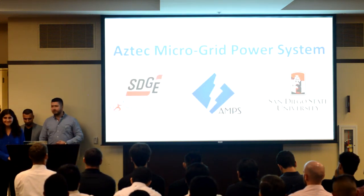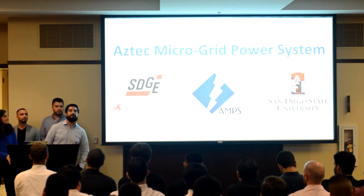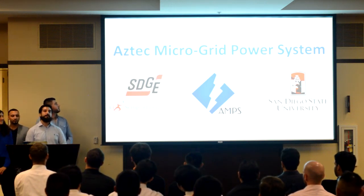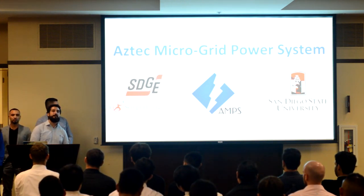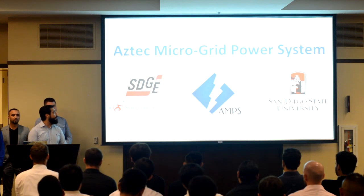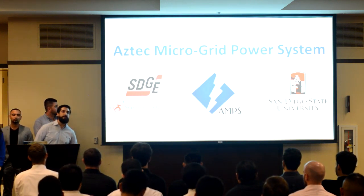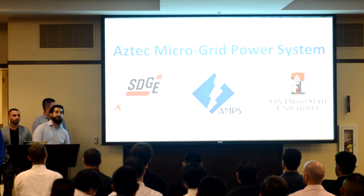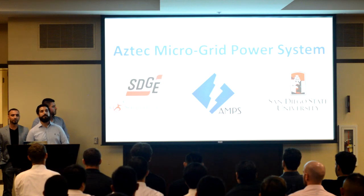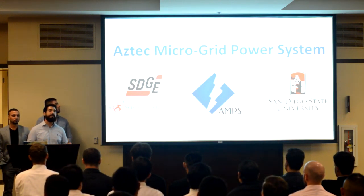Thank you, Sabri. All right, so just to wrap things up, we've designed a miniature power grid system that analyzes the damages done by non-ideal components. We've shown you the negative effects of using modified wave inverters versus a pure sine wave inverter, which only shows the first fundamental harmonic. We also have explained how we can start solving this problem by using filters to start filtering or mitigating out those higher frequencies.